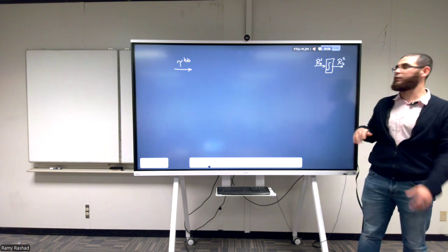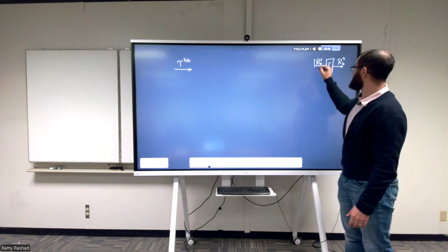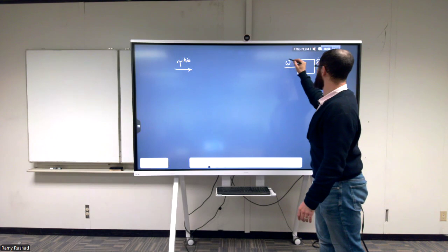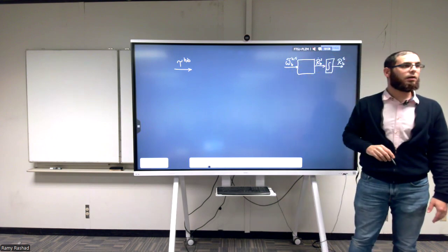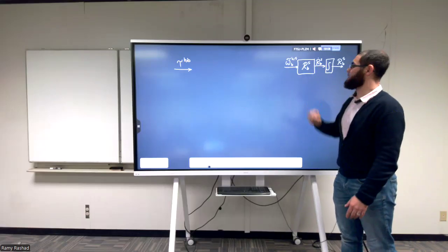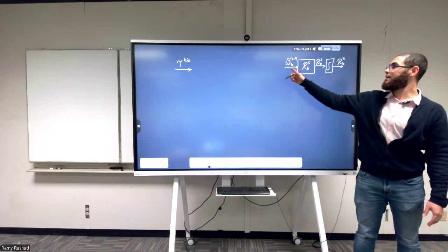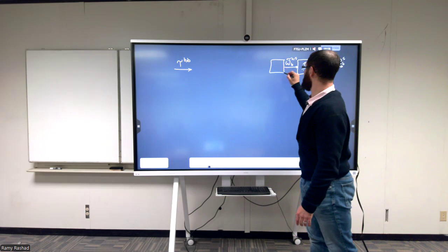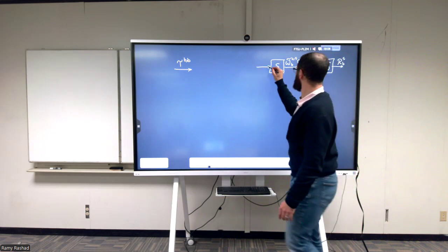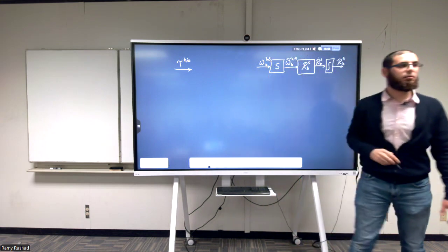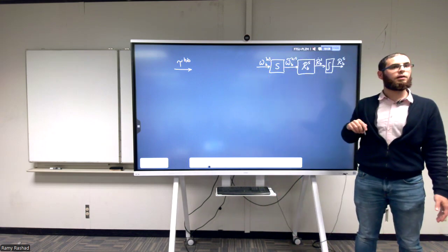But again, in the intuitive sense, I have R dot, and if you tell me omega tilde in the B frame, I can multiply from the left by R BS and relate this SO(3) element to R dot. If you give me the S map and the omega B, which is in R3, I can make it into a skew-symmetric form.